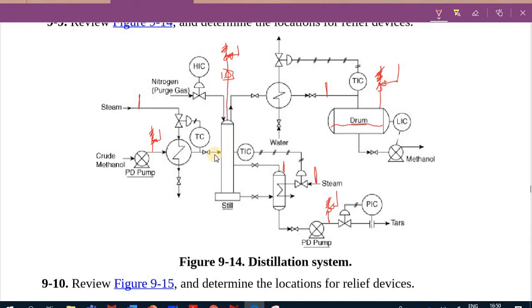Where is the cooling here? I think this is only for a drum. Yep, it's here, I was searching for it. If the cooling shuts down, that means the temperature is going to be much higher. Being higher in temperature, there could be less liquid and a lot of gases, and it's over-pressurizing, and then we open the relief as well. We already mentioned that, but we are just mentioning scenarios, trying to explain what scenarios we can have here.